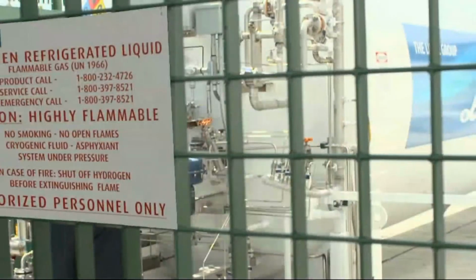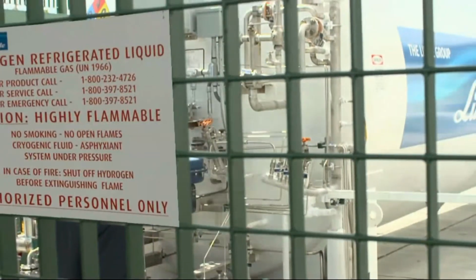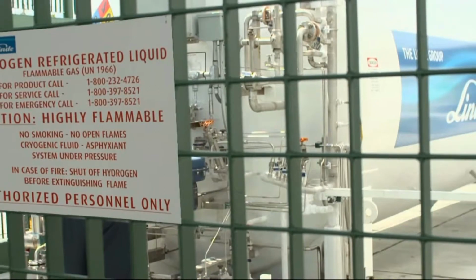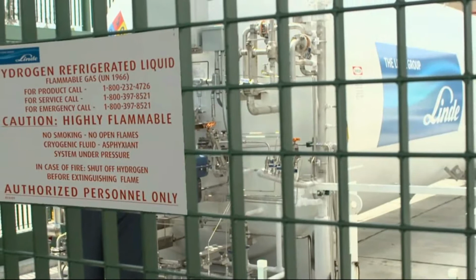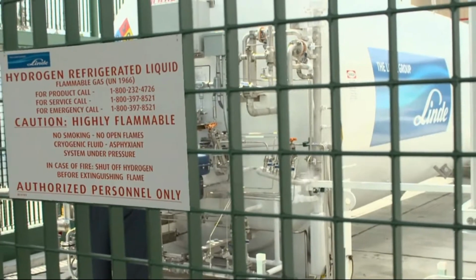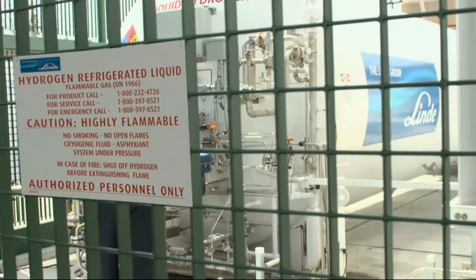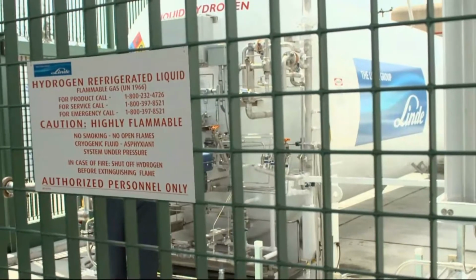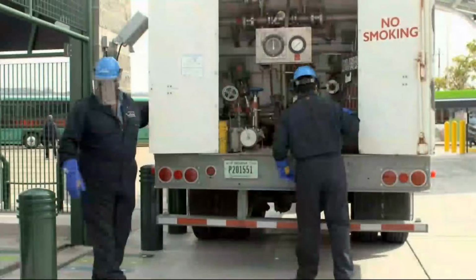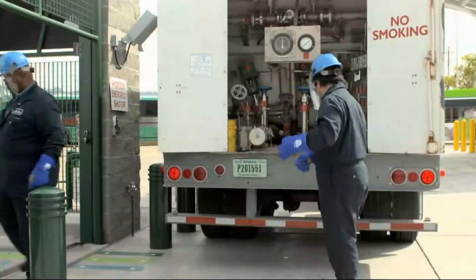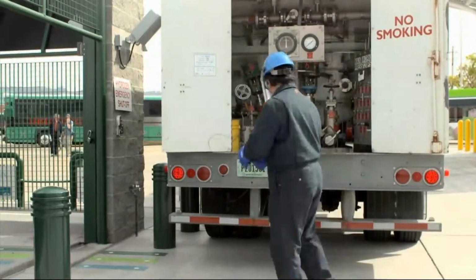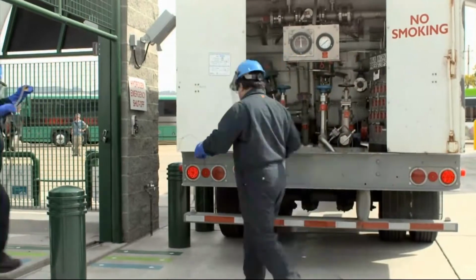Liquefied hydrogen is always stored inside vacuum-jacketed tanks. These tanks are like big thermos bottles, essentially a tank within a tank. With hydrogen, the inside tank is always stainless steel because other metals become brittle at such a low temperature. The storage tank and all other components connected to a hydrogen handling system must be bonded and grounded according to accepted industry practices.